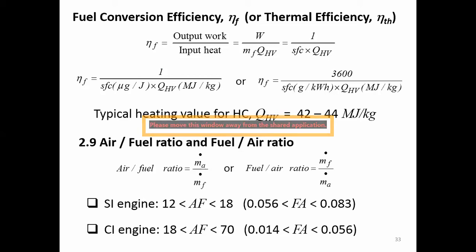Because when we talk about mechanical efficiency, we talk about the same energies, which is work versus work. One is the work input, another is the work output. So it's the same energy that we want to see how it transfers from the origin to the destination. But for the fuel conversion efficiency, this is an energy conversion because we compare two different energies.